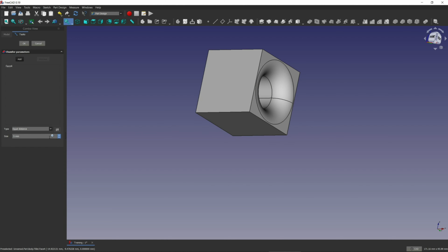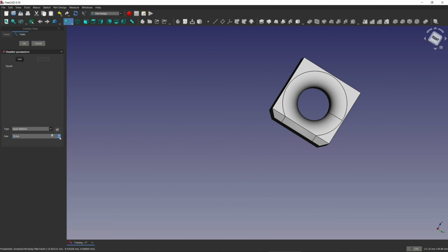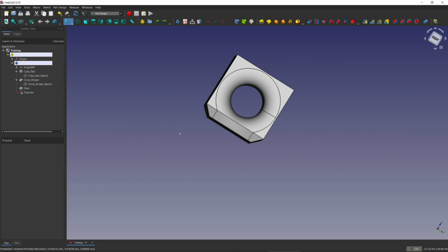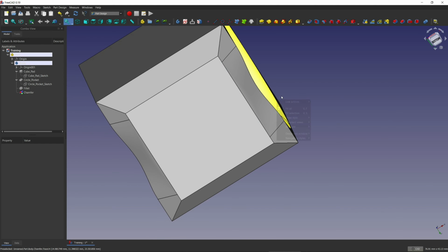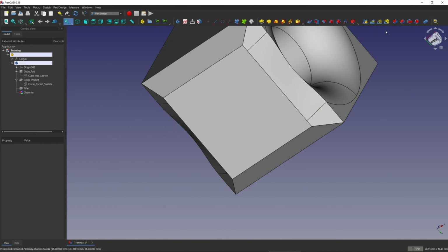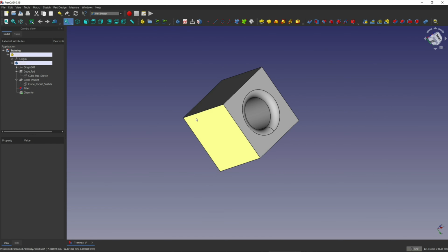And then what you've got on the hole is the fillet, where it's a radius. So with the chamfer tool, you can just bring those edges in, and that will accommodate that extra first layer squish to prevent that horizontal expansion on the first layer. So this was something that, from a 3D printing perspective, I really wanted to know for creating my own models.